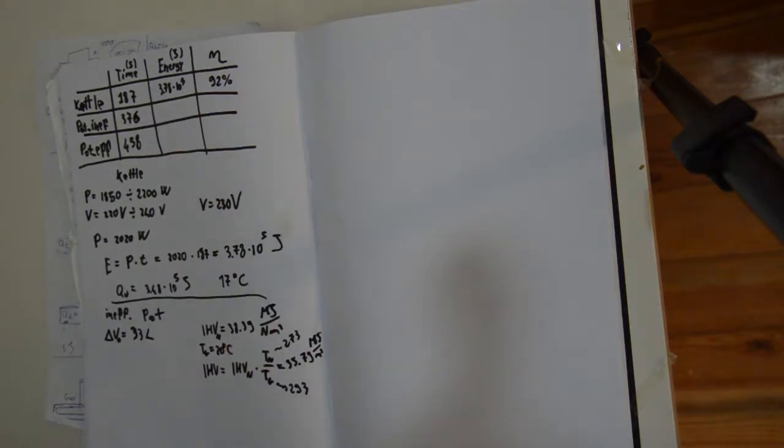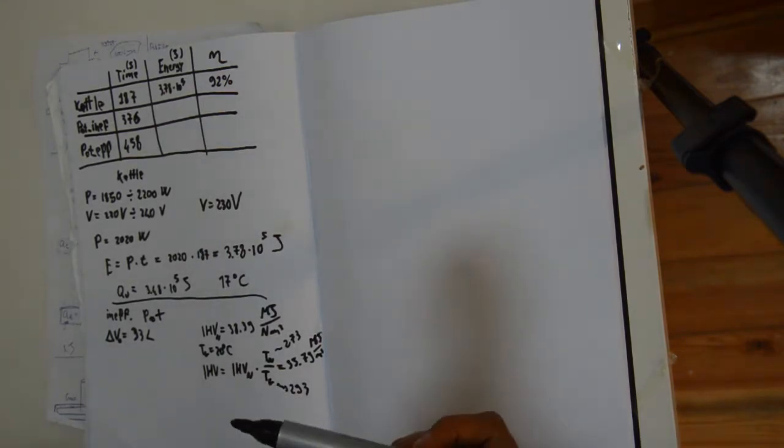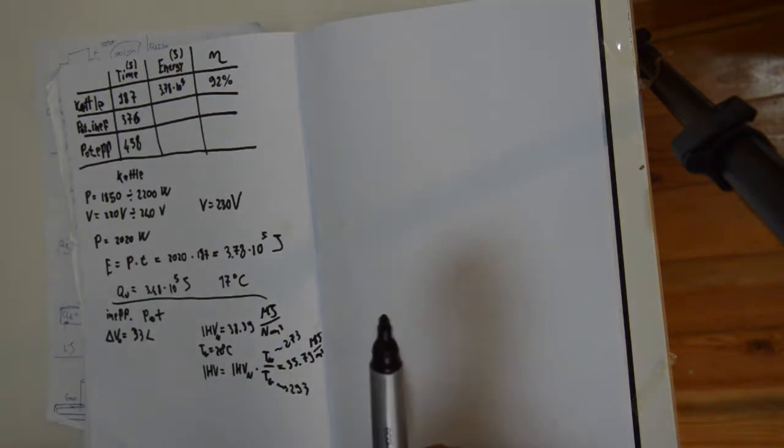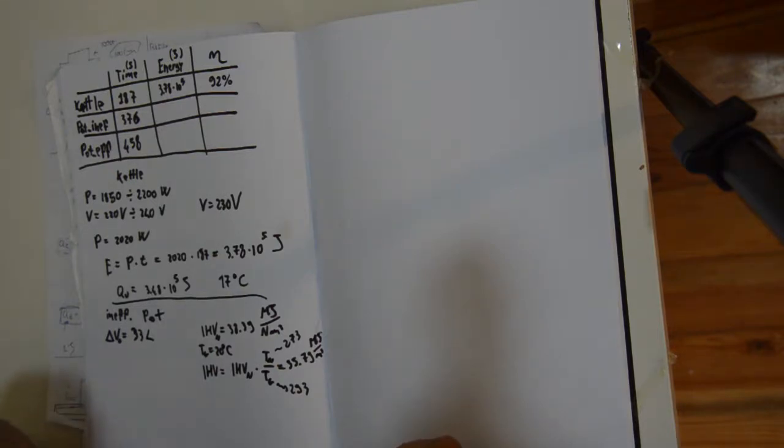Regarding the pressure, we can assume that the pressure is actually pretty close to atmospheric pressure, so we don't need any further adjustment. This is because the gas inside the pipes cannot be at lower pressure than atmospheric pressure. Otherwise, when we open the gas, there will be air flowing inside the pipes instead of gas flowing from the pipes to the air, and this is not possible. And it will be slightly higher than atmospheric pressure, but not that much higher, because it would be dangerous to have high pressure gas inside the pipes. So we can assume that it's almost equal to atmospheric pressure.